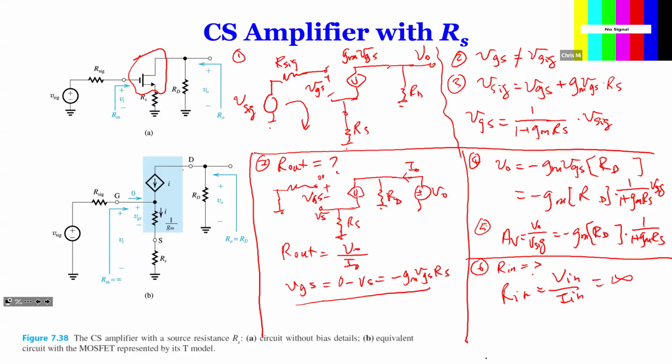But of course, if you go back to the circuit, you can look at it. Well, this is the ground and this is the ground, and you're going from ground to ground, and then you have a voltage drop over here, and you have a voltage drop here. So therefore, the whole loop has 0 voltage. So you can conclude pretty much, yes, VGS has to be 0. So similarly here from this equation, we have to say VGS absolutely has to be 0.